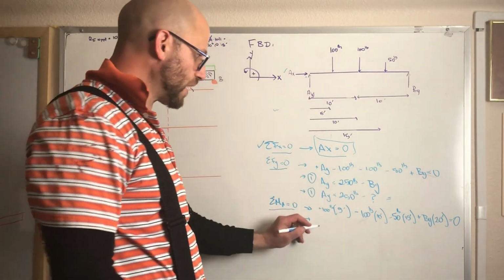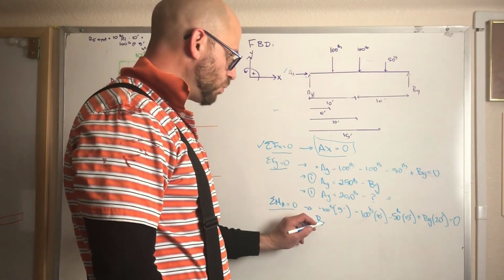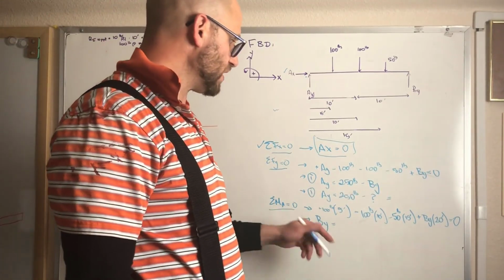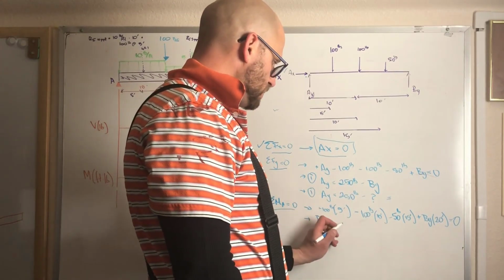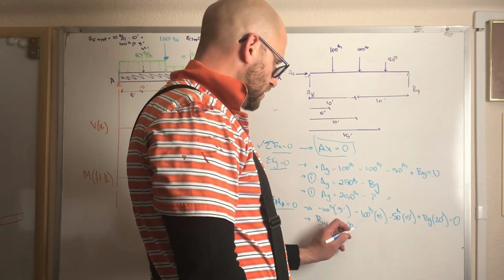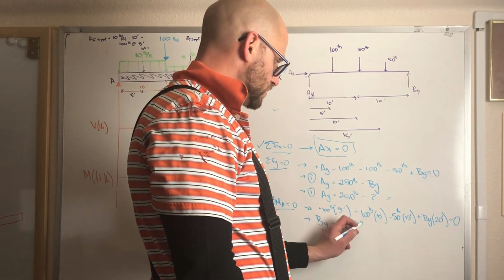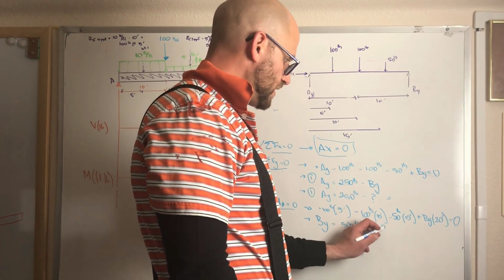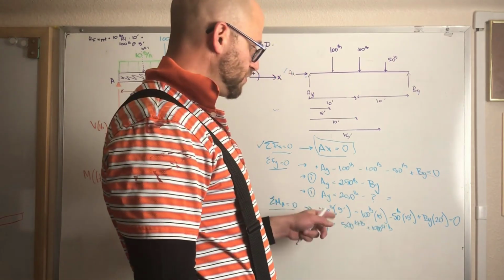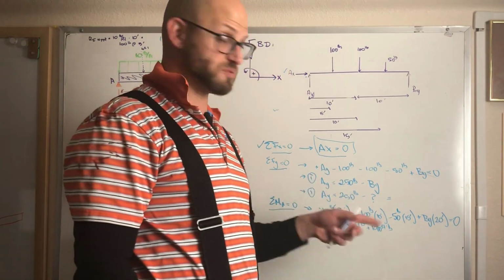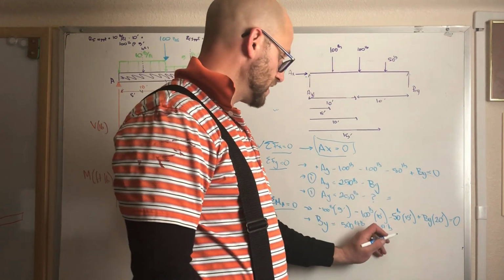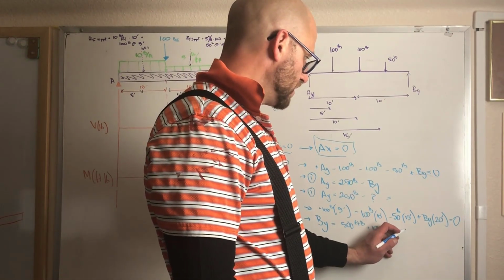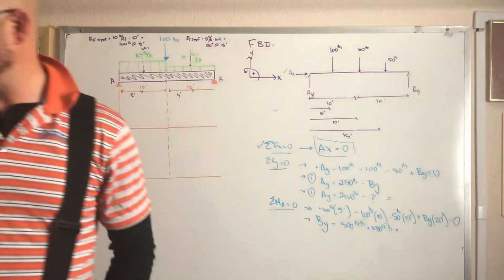Okay, so ultimately what I come out with here is, what does my BY equal? So my BY, if I bring everything over, this is going to be plus 500 foot-pounds plus 1,000 foot-pounds. And again, the reason why I'm at foot-pounds is I'm multiplying my 100 pounds times my distance, and that's what our moment is, force times distance. And then finally, I think that's 750.